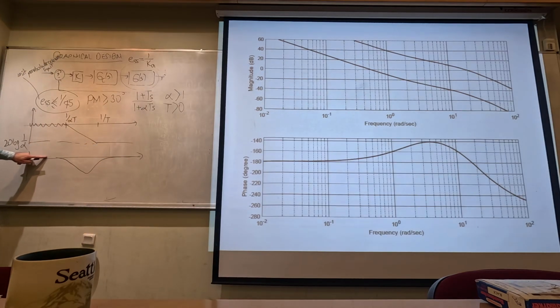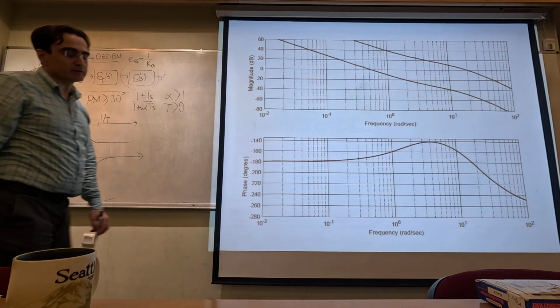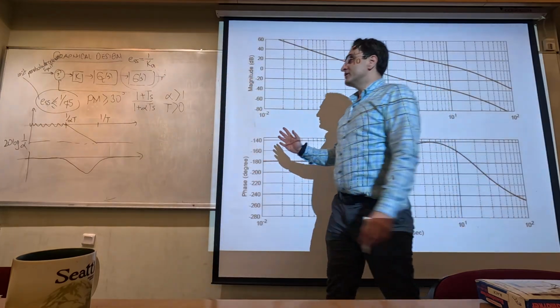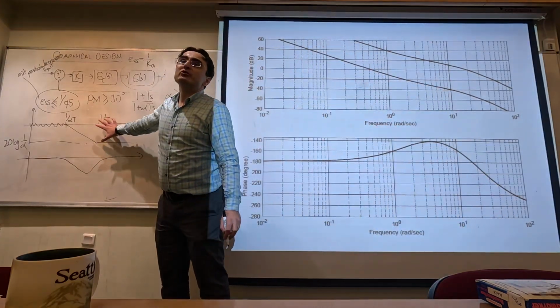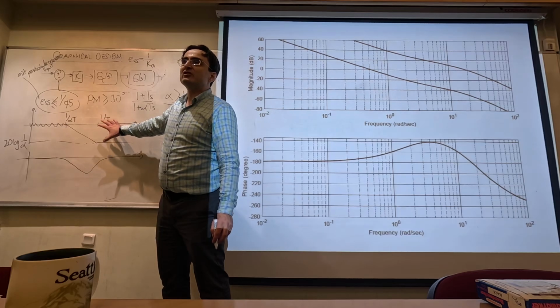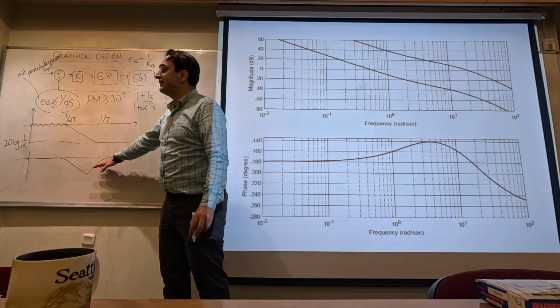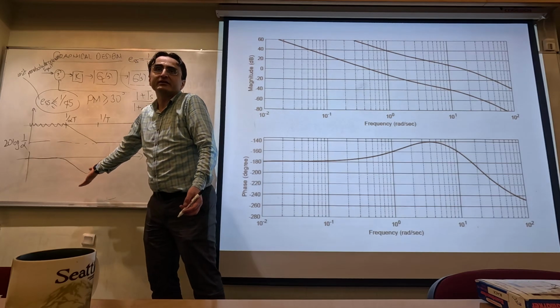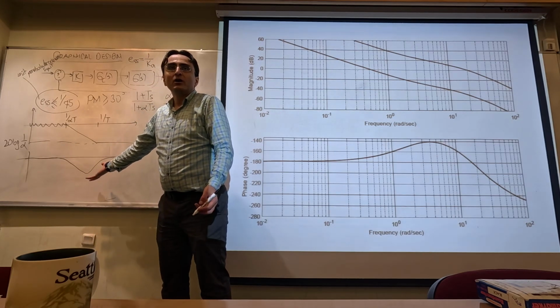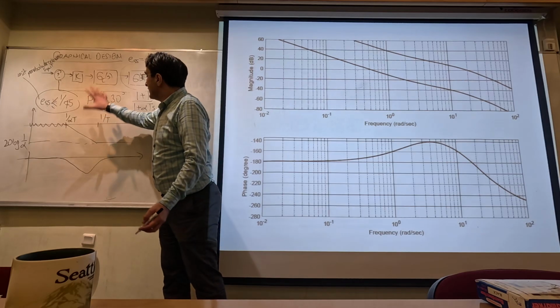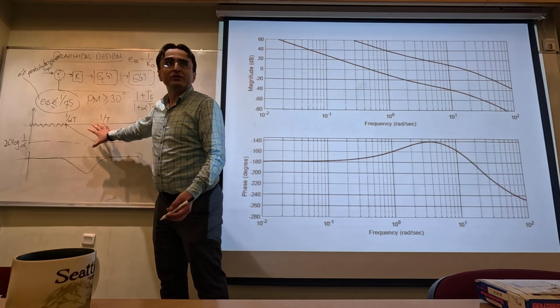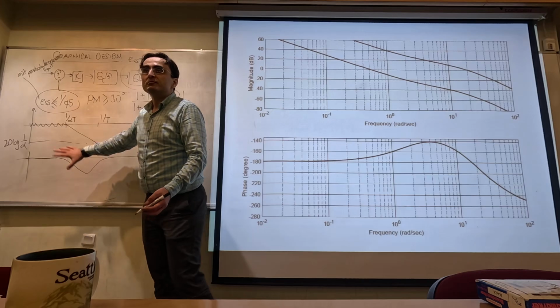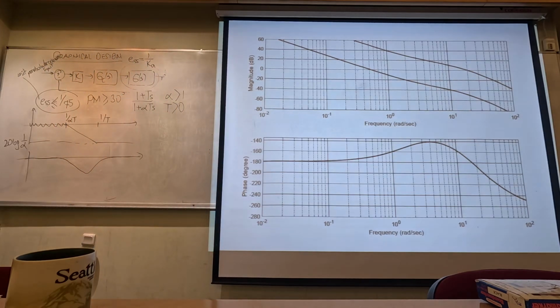And you won't need what phi max is here. It's going to be given with a similar formula, but I won't calculate. We really do not need it. So now, in the phase lag compensator, we are using the magnitude to adjust the phase margin of the system. And then the phase becomes a side effect. Why is that? Because this is reducing the phase. It can actually reduce the phase margin of the system. Okay? That is why we're going to try to benefit from the magnitude, and we're going to overcome the phase decrease as a side effect.